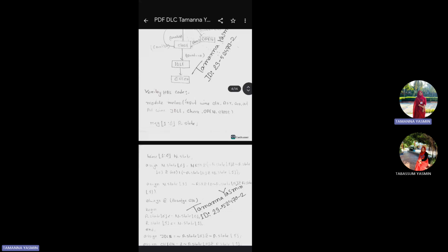The code defines the states using a sequential block to handle state transition on the clock edge and a combinational block to define the output, which is simply to open the gate only when the FSM is in the open state. This creates a clear, reliable control flow for the gate mechanism.